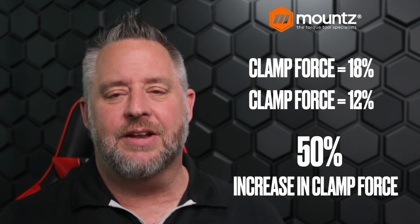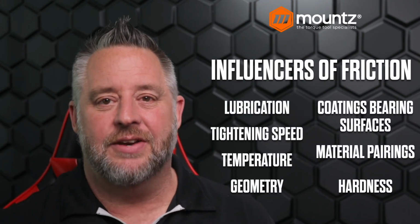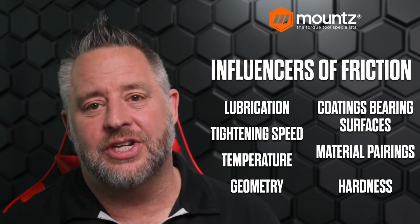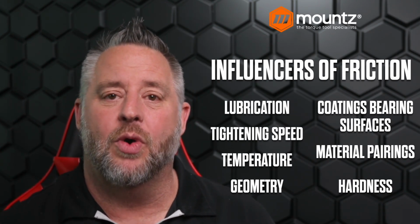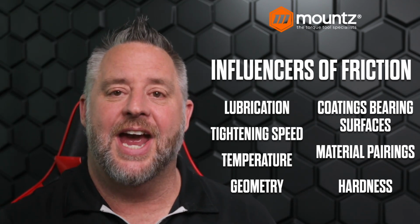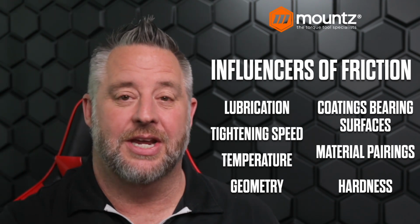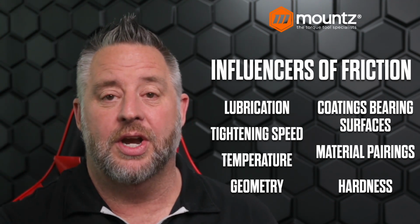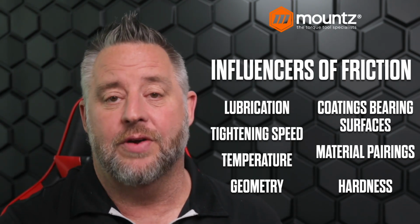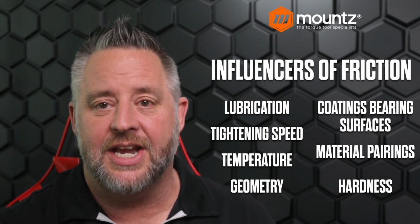Some of the influencers that can cause a change in friction, we typically will see lubrication is going to be one of the highest and easiest things to see as an influencer of friction. Either it's going to allow us to increase our clamp load, or it will decrease our clamp load based on if we're going from a lubricated state to a dry state or a dry state to a lubricated state.